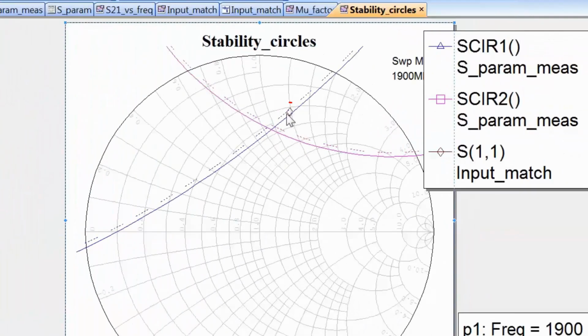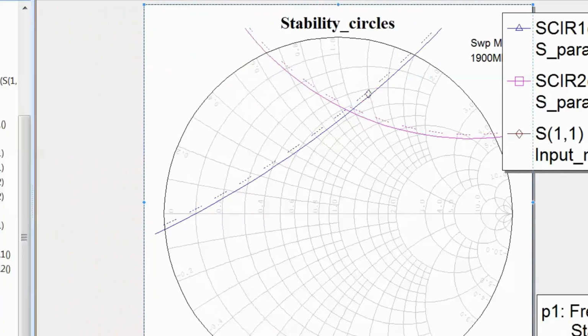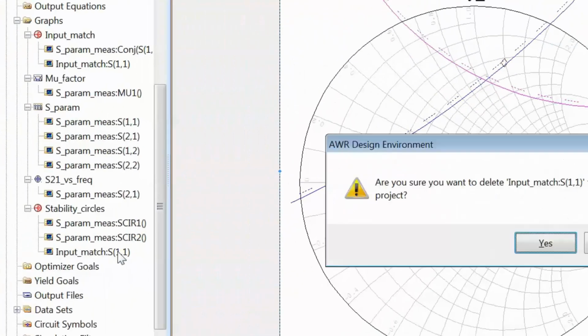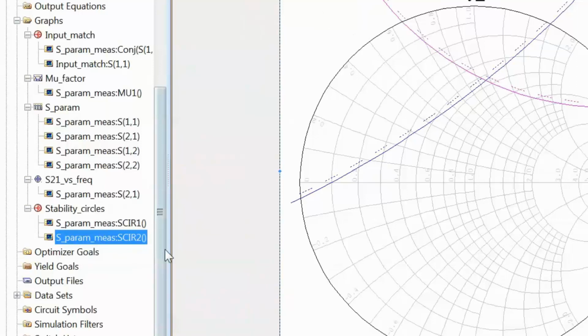Now you can see exactly where it is, and you can see that this termination is in the part of the Smith chart which the input stability circle shows as containing all the input terminations that would make our output reflection coefficient greater than 1, and hence the transistor unstable. So you can see how this actually ties in well with what we did earlier.